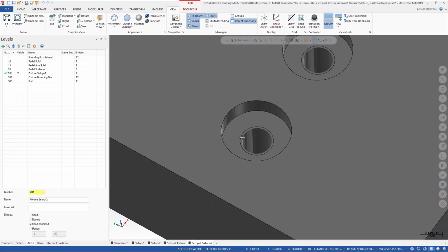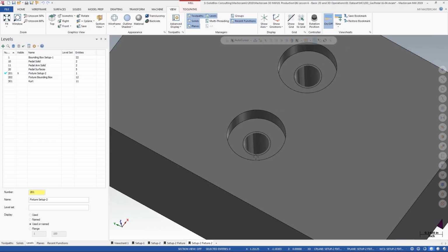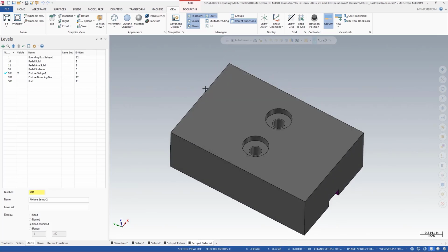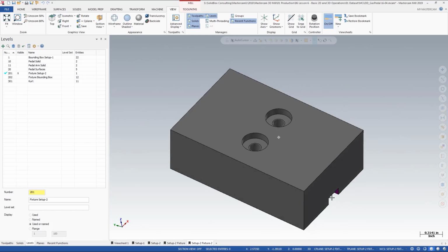In this case, you'll notice that there's a small amount of undersizing that happened on these holes. This sometimes is a good idea when you're making a fixture based on the tolerance of the bolts you're using. To ensure that we have a tighter fit, we could also use countersunk screws or various other methods such as pinning the parts together. In our case, we're going to use the smaller hole to get a tighter fit on the fixture, as well as use the slot to help locate it.